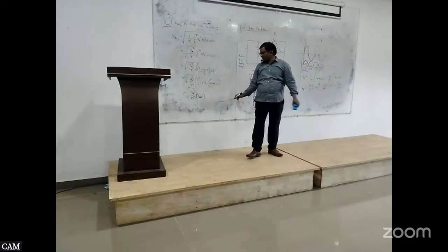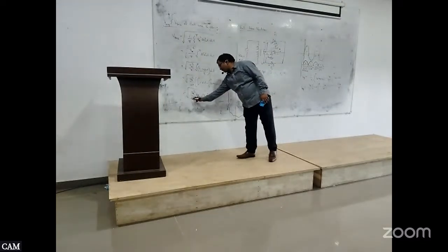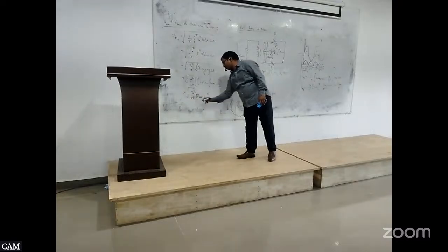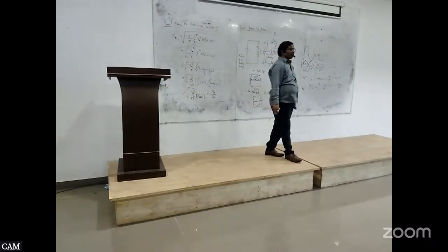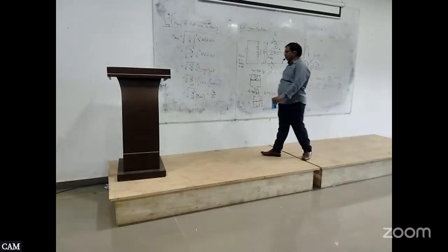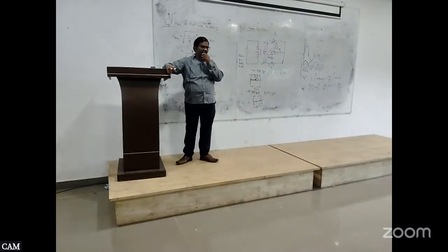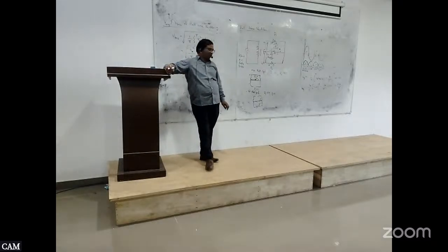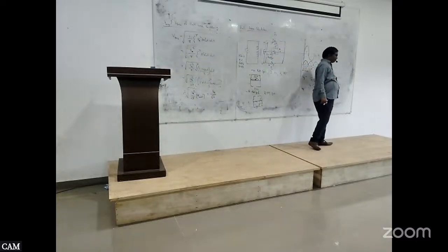From this, pi gets cancelled, and Vm square and root cancel. So Vm by root 2 is the answer. So the RMS value of the full wave rectifier is Vm by root 2, and the average value is 2 Vm by pi.